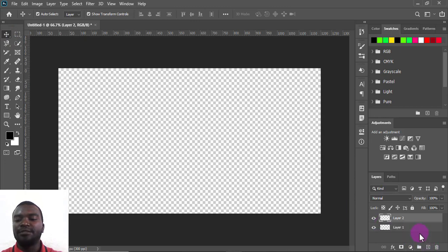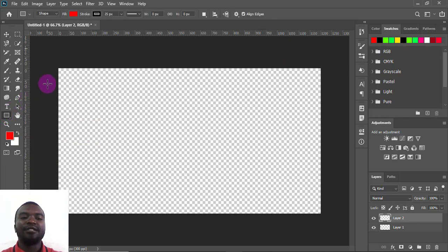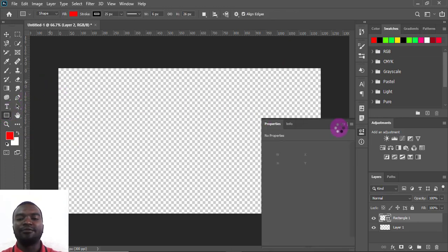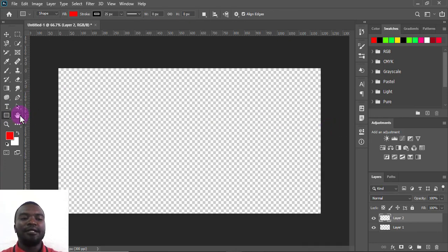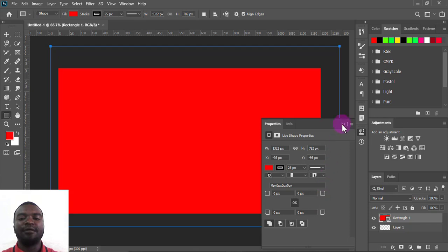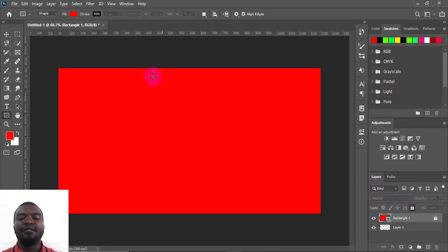So what I'm going to do is put in a background. I'll come here and insert a layer. Then I'm going to make sure my layer is red. I like red for this kind of scenario. So I'll choose rectangle here. The rectangle is going to form part of my background. Sorry, I'll just undo. I'll come again and click rectangle. Then I'll drag it over here so that it forms a basis for my background. Then I'm going to lock it so that it doesn't get interfered with.